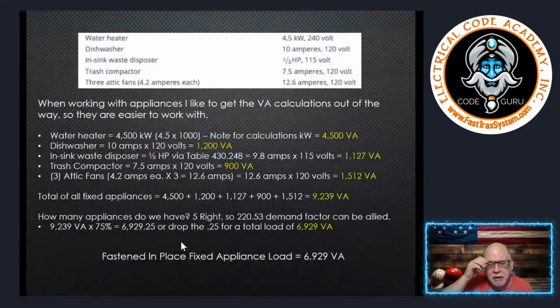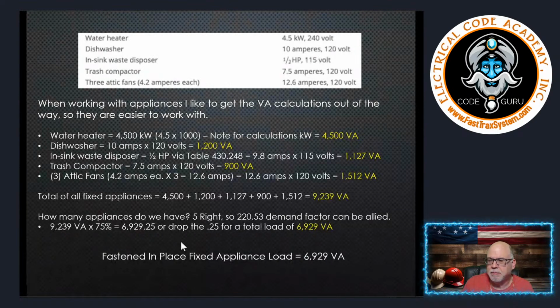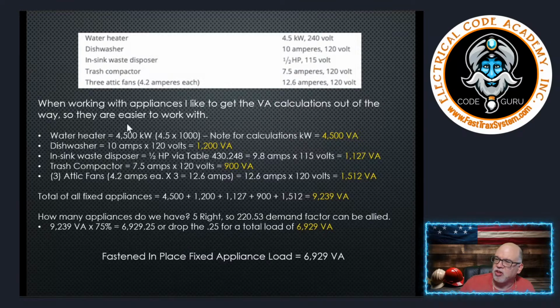All right, so here's what we're working on. You remember? And I've done the math for you. A lot of times on my videos, I say you can pause and work these out, but for the webinar, I wanted to go on and do it, so we've already done it. All right, so here's your water heater, 4.5 kW. Y'all all know that kW is equivalent to kVA. I like to work things in VA because that's typically how we work things when we're doing a load calc. But essentially, the code tells you that they're synonymous.